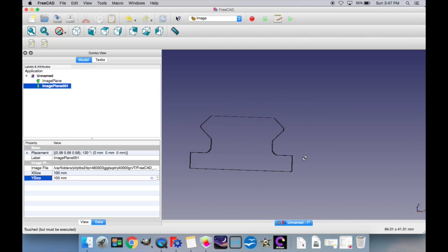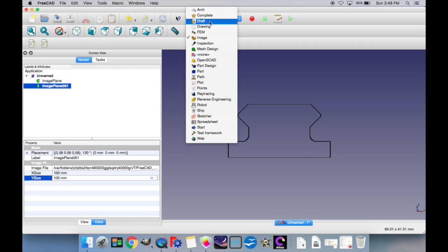And there's another reason I like to center the object in the center of all three axes: when you first do the sketch, you can do half of the sketch and then flip it over to the other side 180, so you don't have to guesstimate where all the points are, and that way you'll have a perfectly symmetrical sketch. So I'll go ahead and start sketching these now, and I'll show you what I mean when I get there.